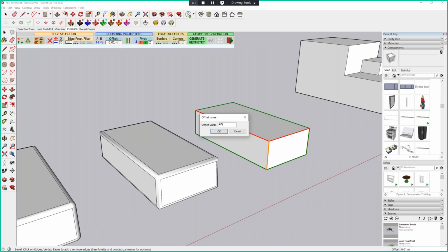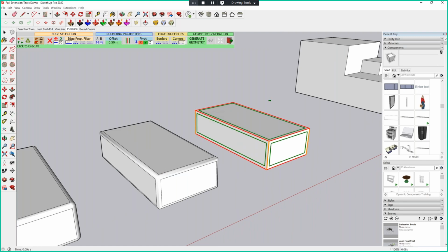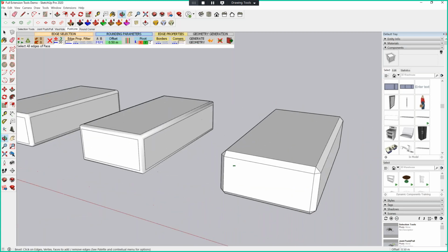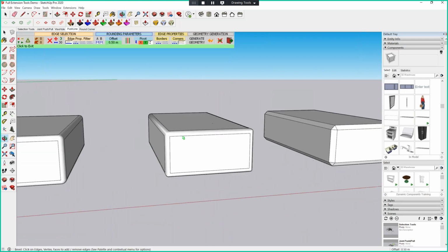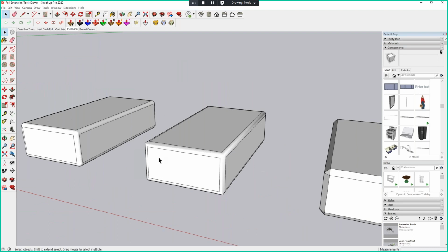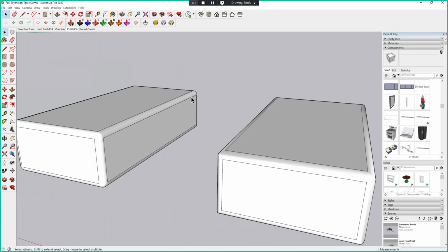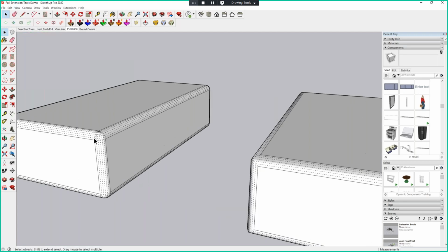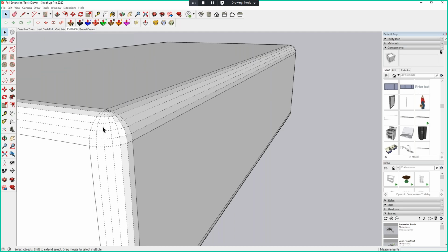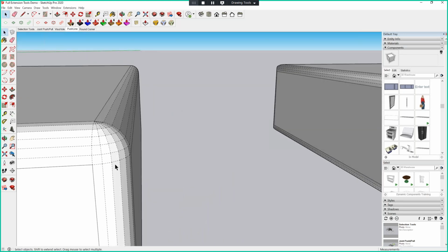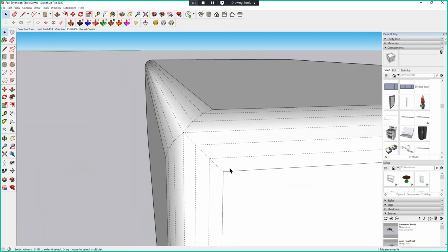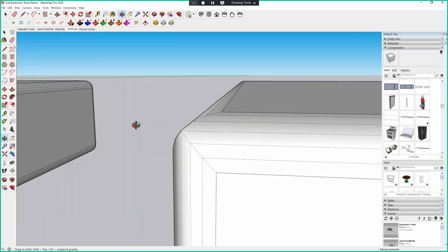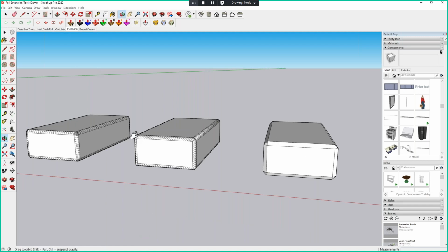Let's change our distance to 0.5, a bigger offset value, enter. So you can see the difference with the bevel. It creates a 45-degree chamfer, whereas with the sharp corner and round corner, you might not be able to see the difference. But let me illustrate it here. Under your hidden geometry, for your round corner, it creates this kind of tessellation or mesh that aims to smoothen the edges of your rectangle. Whereas the sharp corner concentrates on one point to create that sharp corner. So there is a difference between the round and sharp corner.